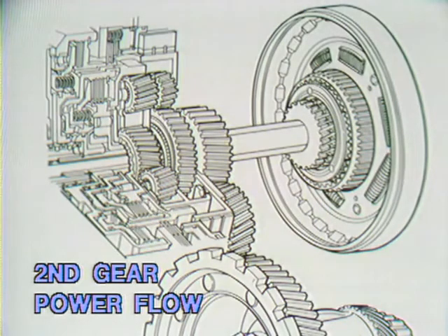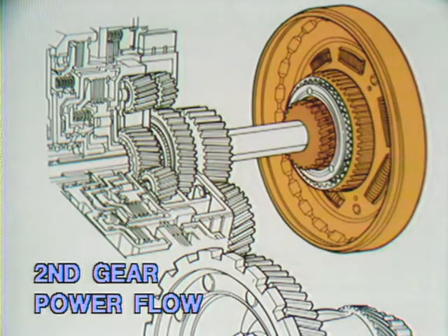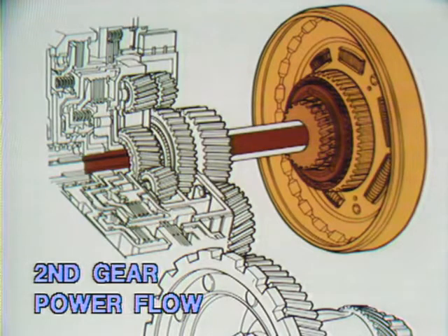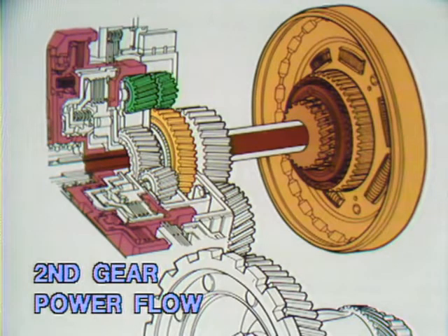Second gear power flow is hydraulic from the turbine to the splitter sun gear, and mechanical from the converter cover, and these are combined in the splitter planetary unit. From the splitter planet carrier, 100% of the power flows to the intermediate shaft, through the intermediate clutch to the ring gear, to the long pinions which again walk around the sun gear, to the pinion carrier, and to the final drive gears.